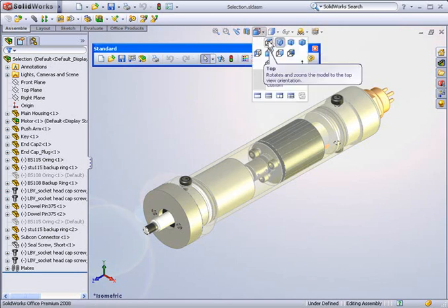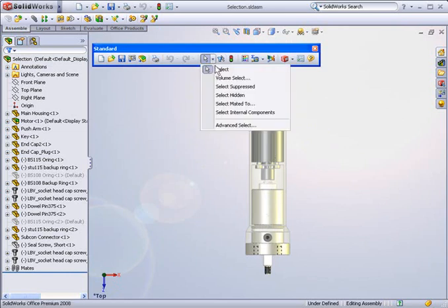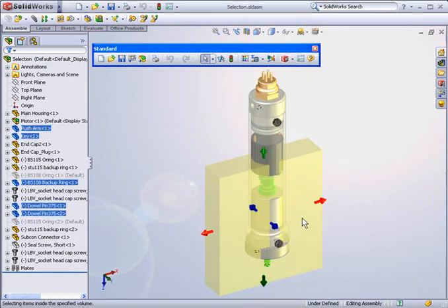To use the volume selection, it is probably best to switch to an orthographic view first, and then draw a selection volume box. The viewpoint will then change to a 3D view, and your volume box will be displayed. Any components that the volume totally encompasses will be selected. Note that components that cross the volume are not selected.